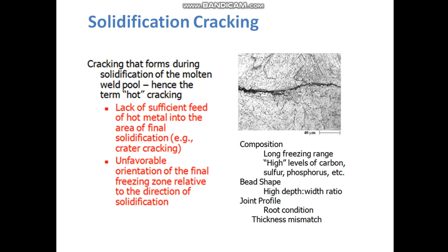When the weld heat source approaches the end of the weld joint, crater formation takes place, and the hot metal will not feed the depression or backfill the crater or cavity.